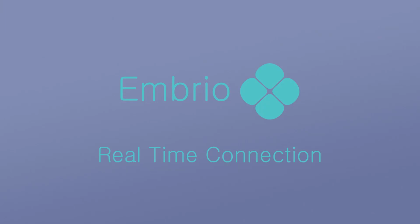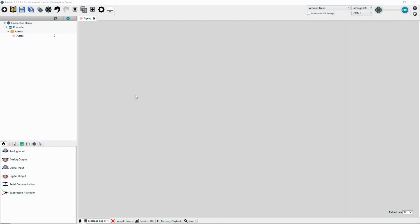Alright, in this video I'm going to show you how to quickly get connected to an Arduino and work with real-time data. First I'm going to start by controlling the built-in LED. So I start by going to the I/O menu and drag a digital output onto my screen. On most Arduinos, including the Nano which I'm using, the built-in LED is on pin 13, so I'm going to leave that as it is. And then I'm going to connect.